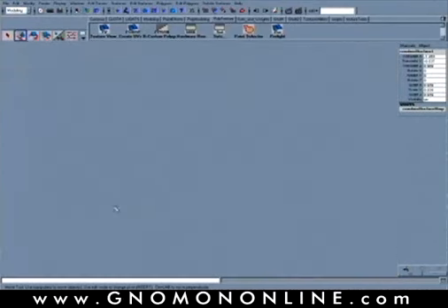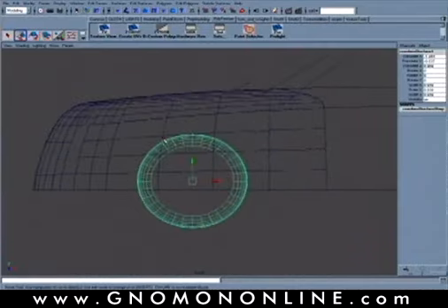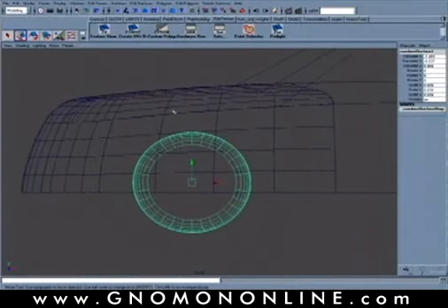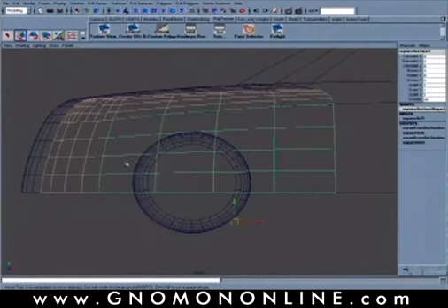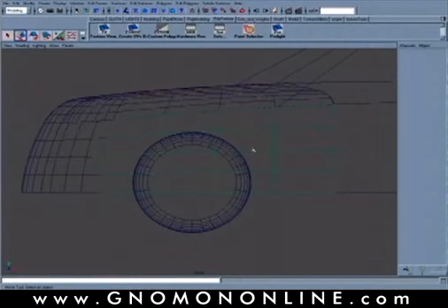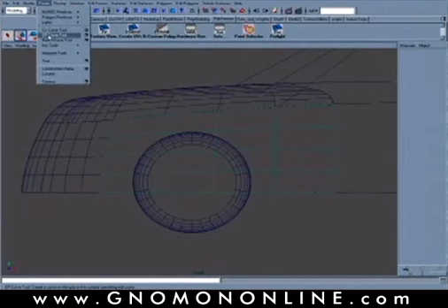So first thing I'll do is in the side view, I'm going to design how I want the outside wheel part to begin coming off of that other surface. So we can do this either by making this primary quarter panel live. So if you hit the Make Live selection tool there, and then I'll go in with a new curve where I can basically create with an edit point curve. That's kind of my preference when I'm trying to get more accurate snapping modes to the surface.